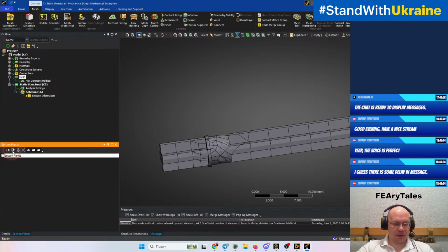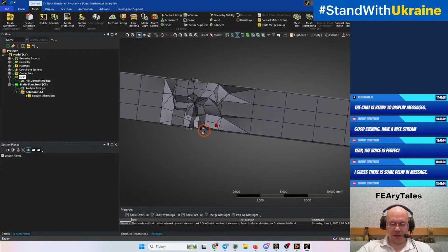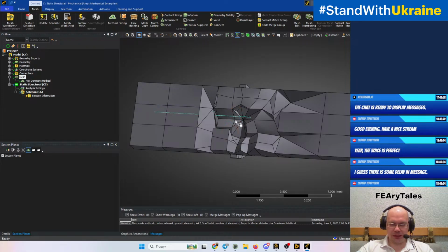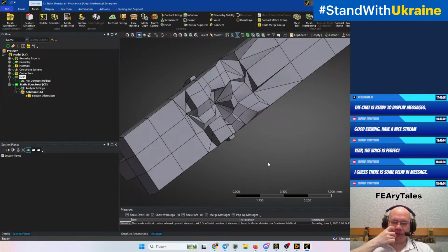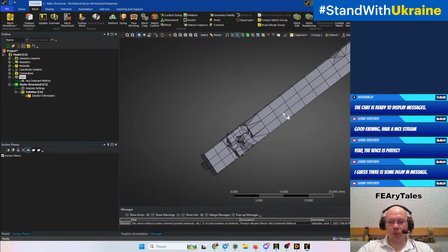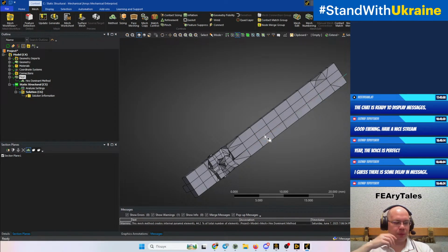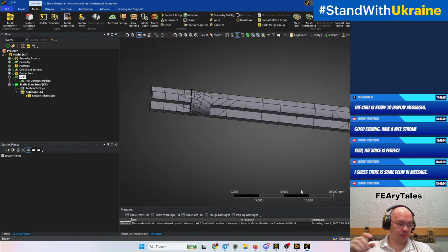And if we create the section view, we will see that in some places we have very strange tetrahedral and hexahedral mesh, and even for a simple hexahedral object like the cube, the hex dominant mesh will create inside of this cube very strange mesh because of the method of how it creates. Because firstly it creates, in most cases.